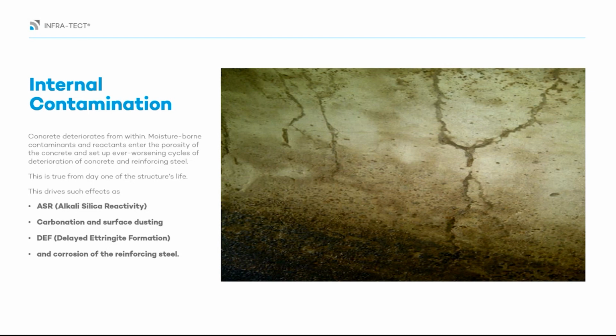So it can start from day one. You get things like alkali silica reactivity. That's when the silica is highly reactive and can expand. There's things like surface dusting, carbonation getting into the concrete. Things like the corrosion of the reinforcing steel is something that everyone's familiar with because it's the thing that we see once it actually comes through. But the biggest thing is it's moisture that brings in things that aren't designed to be in that concrete mix to start with. So moisture brings in all sorts of different contaminants that have reactions with either the sand or the reinforcing steel, again, the one that everyone's really familiar with. And it can start at day one and it just keeps building and building.